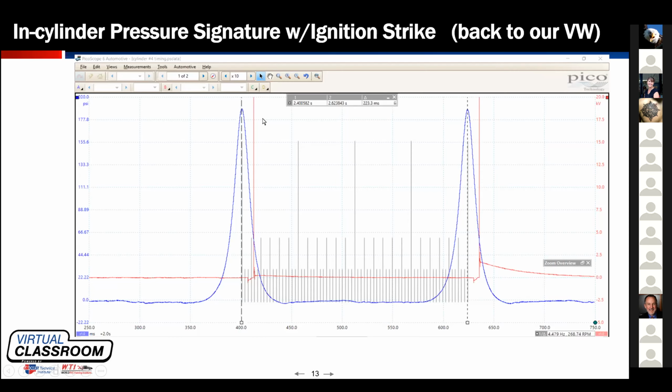But this dictates an absolute lie from my scan tool data as I see with the raw data on my scope. My dude in the dash said, Adam, we believe we're 7 degrees before top dead center. That would have put that strike over here before the top dead center marker. But contrary, this is, gosh, guys, I don't know if you can read these numbers, but I'll tell you, this large mark right here is 30 degrees after top dead center, and it went another 10 after that. This timing is actually 40 degrees after top dead center.